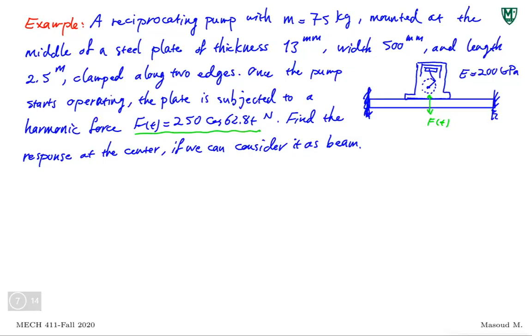So Ft. Now I want to find the equivalent of this. Hopefully you remember stiffness. If this is a mass, it's a spring fixed there, and then I have some force applied to it. This is nothing but, call this K equivalent, my spring mass system. It's a totally different problem, but I can easily boil it down or simplify it to a spring mass system with a harmonic force excitation. So the first task would be to find a K equivalent. And K equivalent for this one,